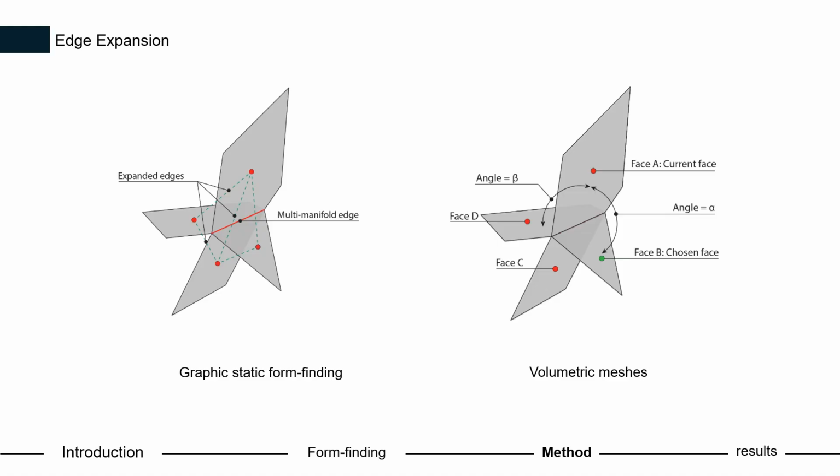We then weight both standard and expanded edges using dihedral angles in order to have smoother transitions, which get lower cost, and topological proximity, a penalty if there are many faces in between around that shared edge. Finally, a Kruskal style growth merges faces across the lowest weight edges, and this yields connected fabrication-friendly segments.